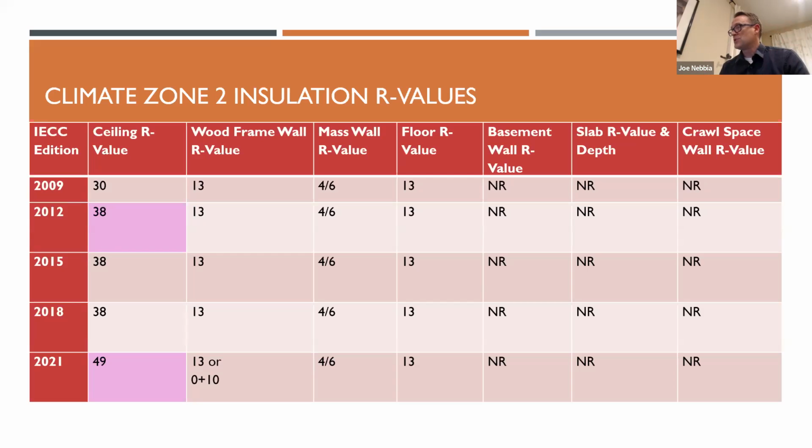The R value is just talking about what the label on the product says it is. And that product has to be tested according to FTC rules. It can't just claim any R value, which does happen with some of the less scrupulous products out there where they're claiming an R value that's not actually according to the FTC tests.